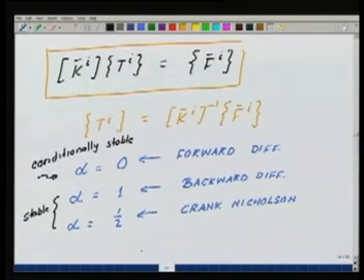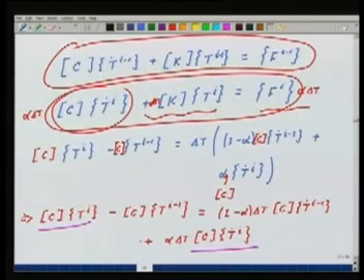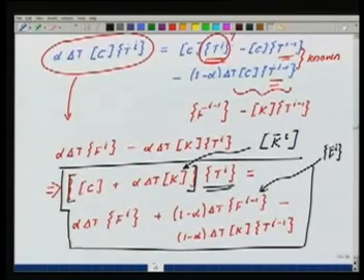If I go back to our representation here, where is my equation? Okay, here, this part will get knocked off. So I'll get C into Ti is equal to, this will not get knocked off, delta T f at i minus 1, minus delta T k into Ti minus 1. This is a matrix vector multiplication. So all we need to obtain is k into Ti. We do not have to invert k.